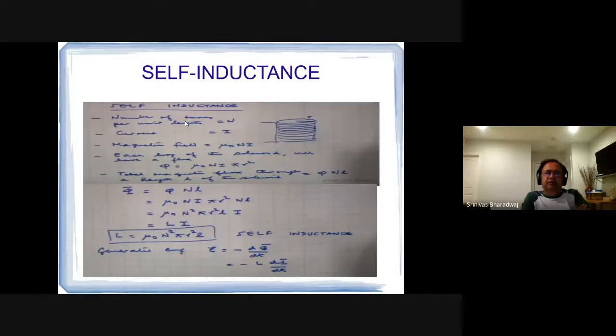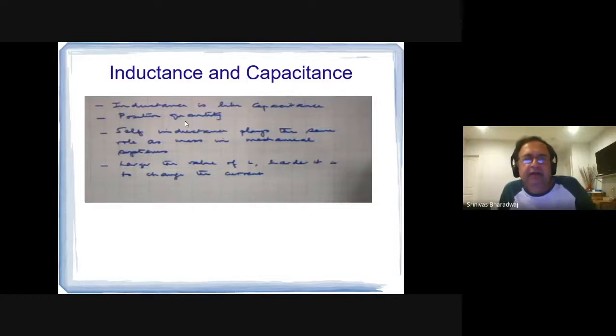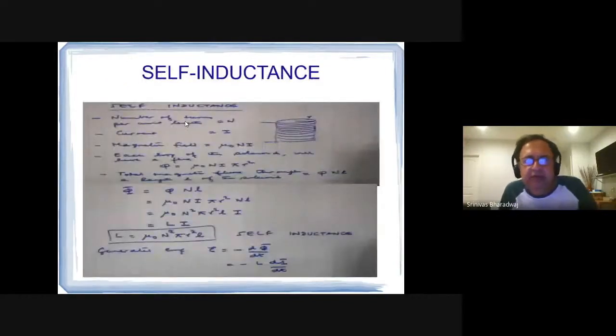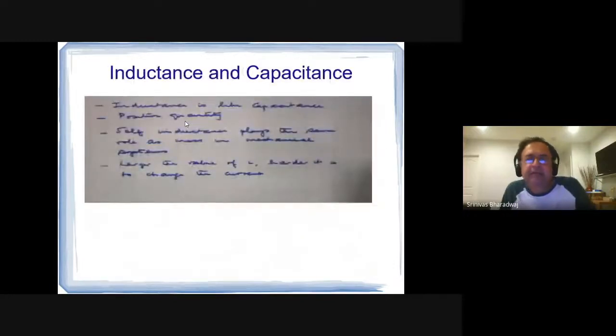Okay, so there is a self-inductance, which is why we have this thing called the inductor coil. Now, an inductor is the counterpart of the capacitor. Q equals CV, so dq by dt equals C times dV by dt. That is the equation for the capacitor. Now phi equals Li, and d phi by dt is equal to E, so V equals L di by dt.